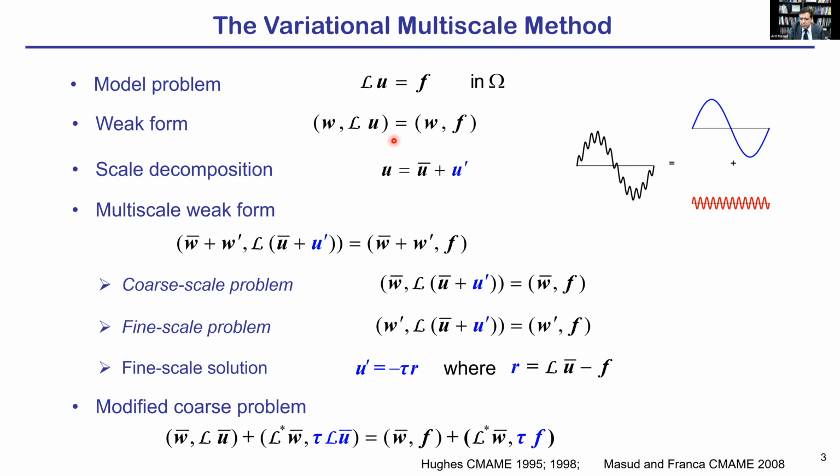We make a mesh, we solve the problem. Now this signal here shows the overall signal, and with a decent mesh and a good method, we are able to capture the mean feature, and the small fluctuations about this mean are filtered out. And if you want to capture the small fluctuations, we normally need to refine the mesh. But this line of thought can be fairly restricting because we need finer and finer meshes if we want to capture finer physics.